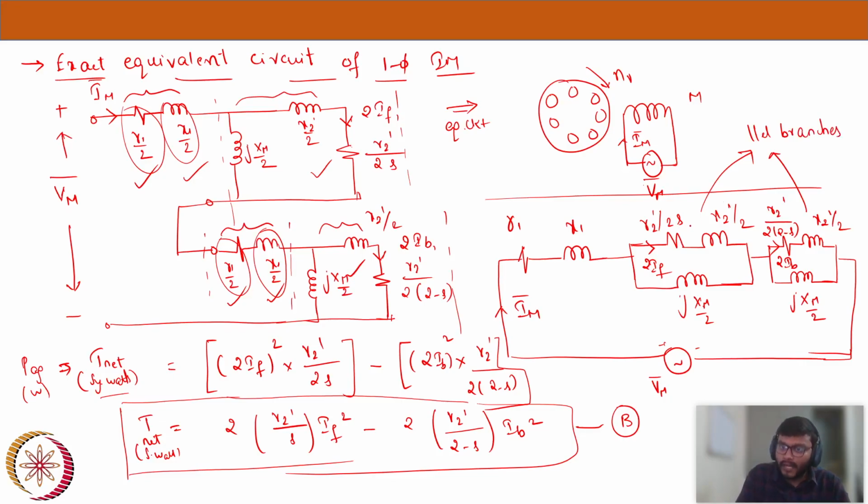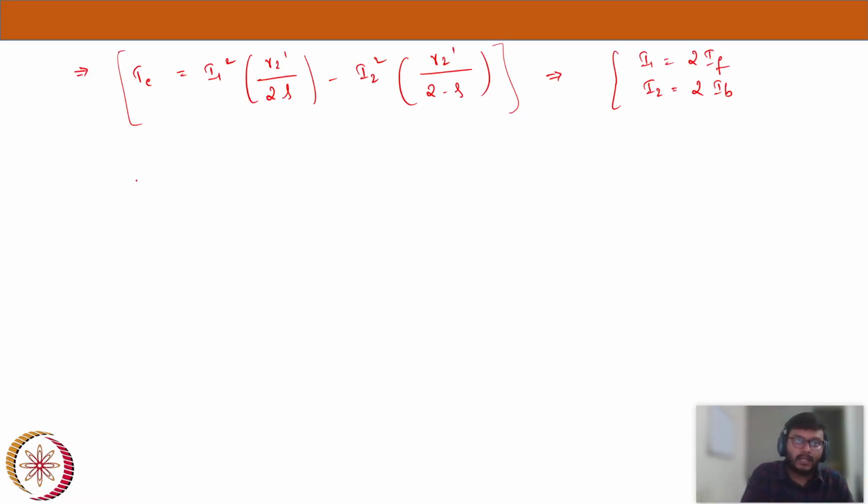If we can find an equivalent impedance of it, let's say the forward field's impedance, we can say ZF, and the backward field ZB, I mean RF plus jXF, and RB plus jXB, we can replace our circuit with that. I will quickly draw this little part.